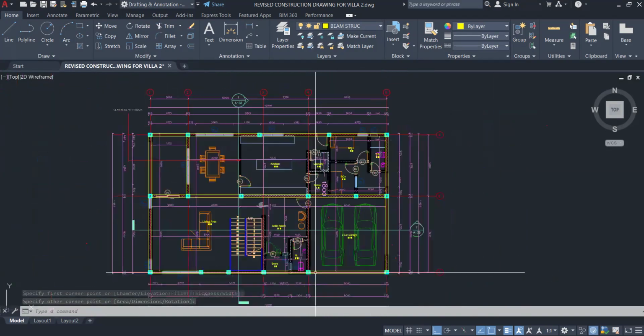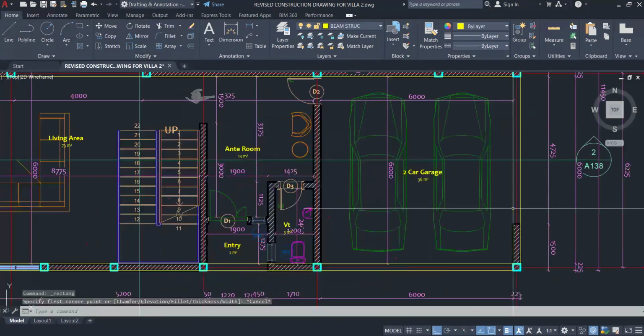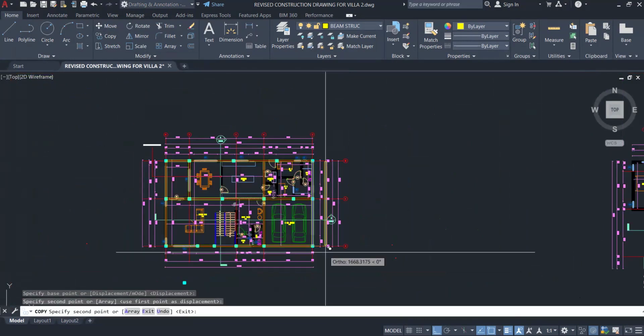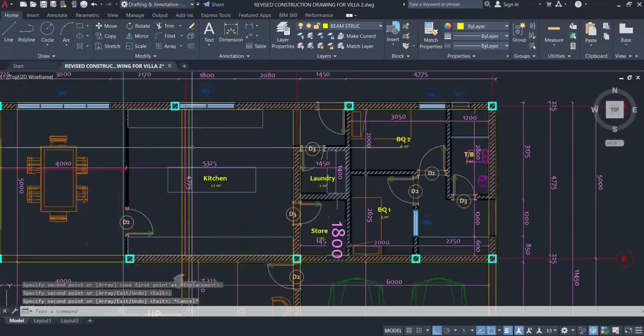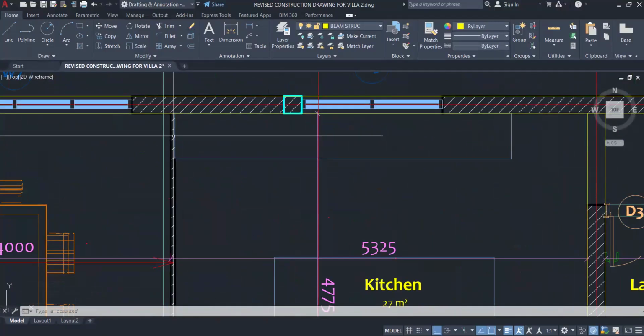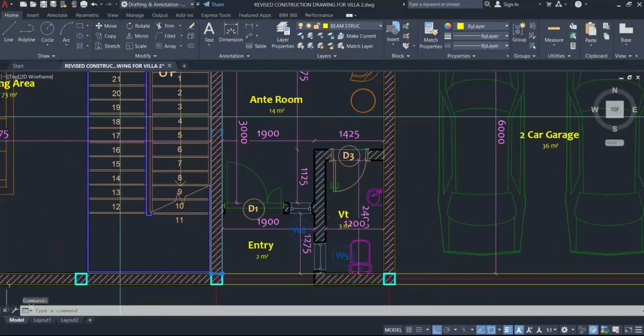Then this is another wall that is going straight up. So I will put another beam, or let me just copy it. So this is the beam connecting it. So this is another beam here. But this beam, I will terminate it here because I don't want it to be coming out of this kitchen area. So I will terminate it like this. Then I will put another column on this wall, even though this wall is not completely a full normal wall, but your beam will be like that.